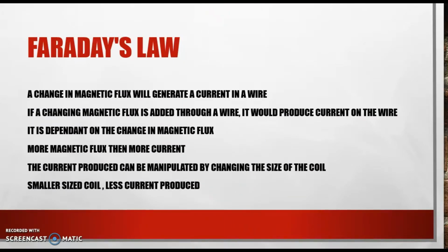So today I'm going to talk about Faraday's law. Faraday's law of induction is a basic law of electromagnetism predicting how a magnetic field will interact with an electric circuit to produce an electromotive force, called EMF, a phenomenon called electromagnetic induction. It is the fundamental operating principle of transformers, inductors, and many types of electrical motors, generators, and solenoids. The Maxwell-Faraday equation is a generalization of Faraday's law and is listed as one of Maxwell's equations.